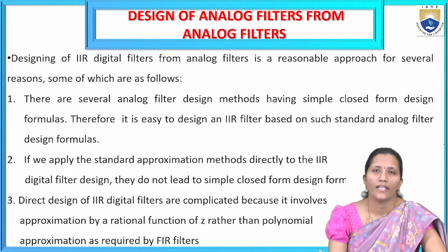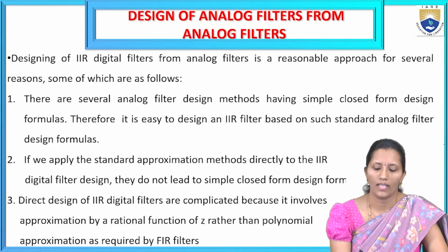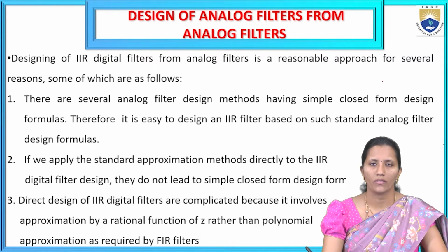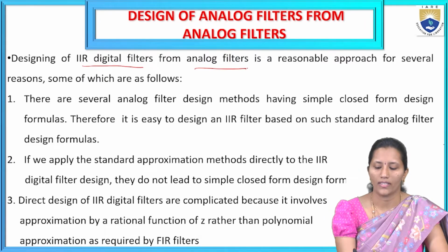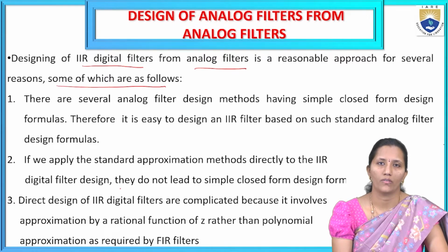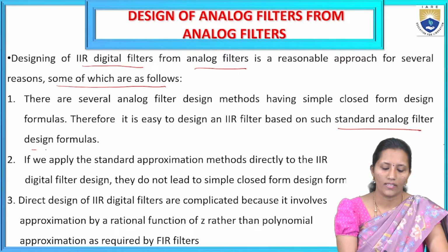Now, the designing of IIR digital filters from analog filters. While designing IIR filters, first we take the analog filter prototype. Designing IIR digital filters from analog filters is a reasonable approach for several reasons, some of which are as follows. There are several analog filter design methods having simple closed form design formulas. Therefore, it is easy to design an IIR filter based on such standard analog filter design formulas.